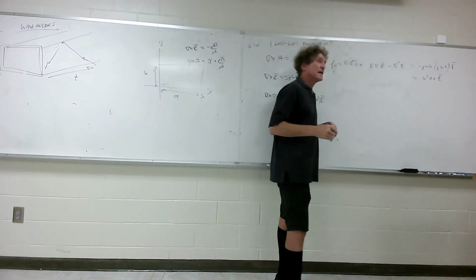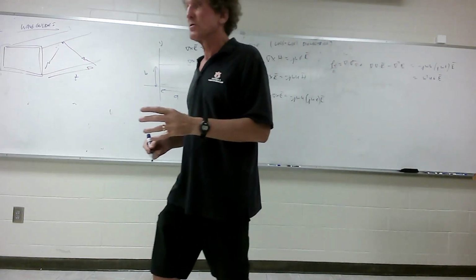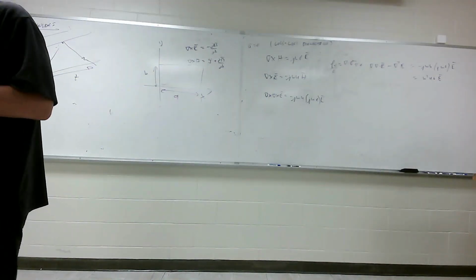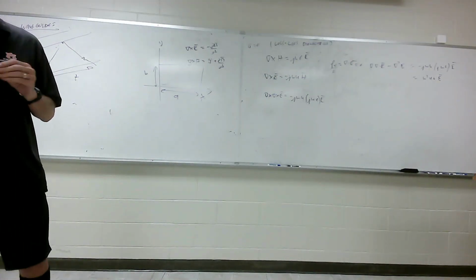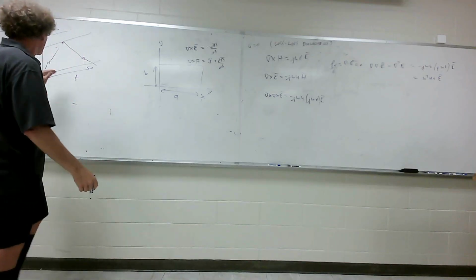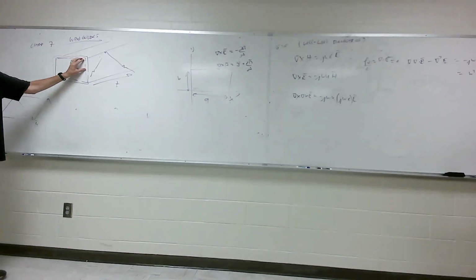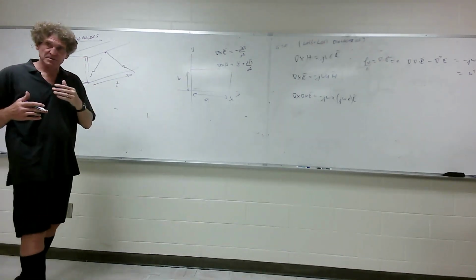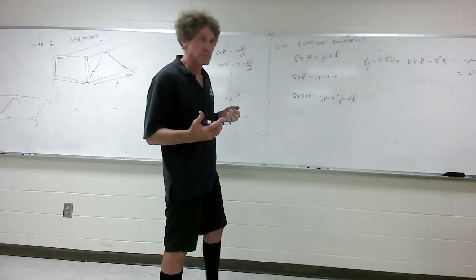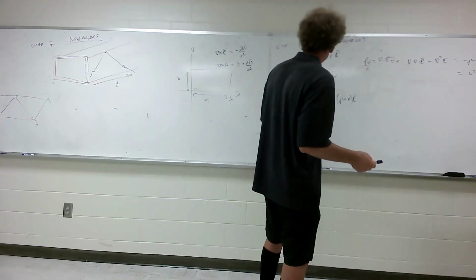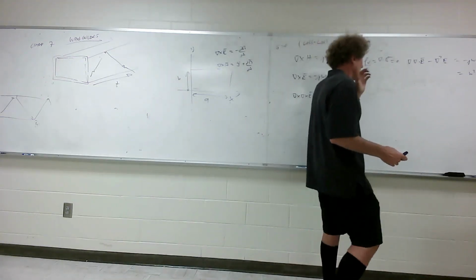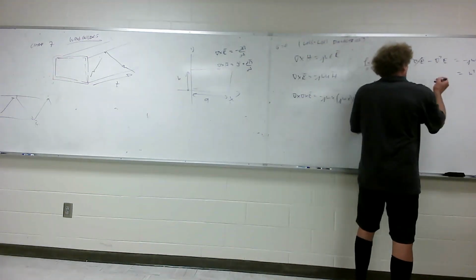Does everybody understand that there's Gauss's law, divergence of D is equal to rho V, and if it's charge-free, it means in this dielectric, in the region inside this rectangular pipe, we're assuming that there is no bound charge, which is a very fair assumption. So we get that it's equal to 0 right here, and that means this goes away.